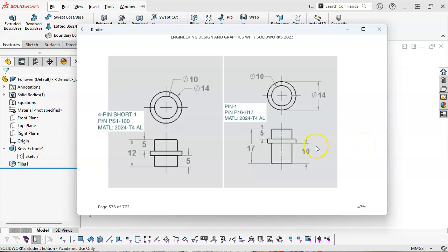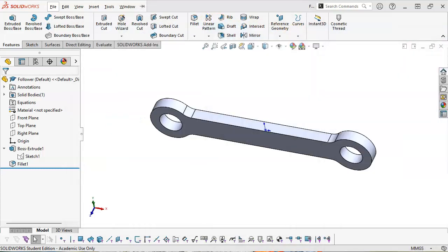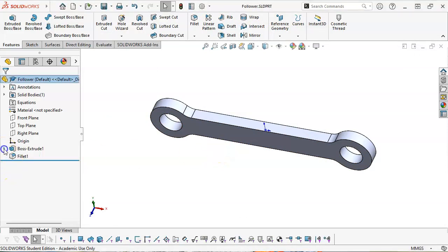If we do this as a revolve, I would tend to want to do the math. Make this a derived driven dimension, and our flange is going to be 2 millimeters, so that I can easily change from 5 to 10 or from 10 to 5, whichever way we go. We have 14 and linear dimension versus the diameter, not a big deal. 10 millimeters on the inside, and then we'll need to kind of make a decision about the tolerance of which way those are going to go, since we're not doing bearings on these guys.